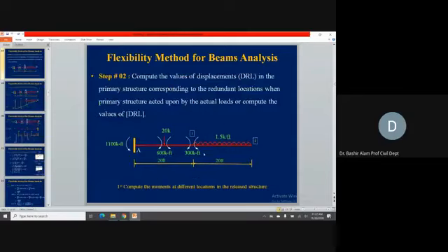How is the bending moment diagram drawn? We go back to this slide now. At each section, we find out the bending moment values. Directly you can do it like this: 300, how is it coming? It is coming from 1.5 times 20, which is the equivalent point load here. So 1.5 times 20 is 30, times the moment arm. The moment arm is 20 divided by 2, which is 10. So 30 multiplied by 10 gives us 300 kip-ft.